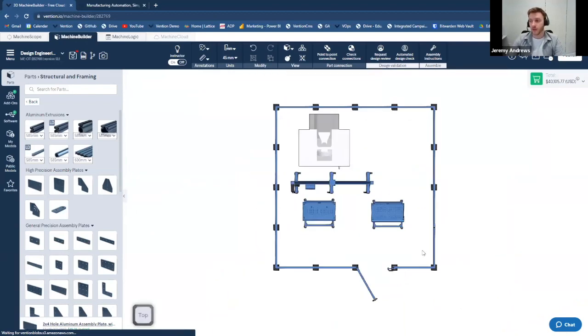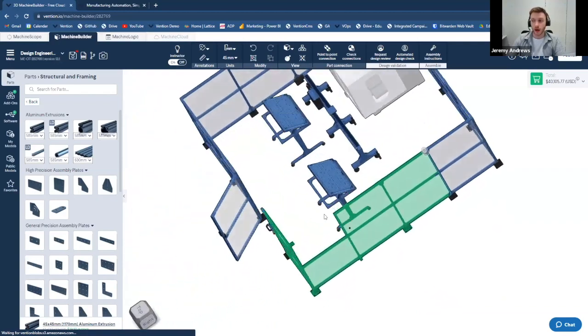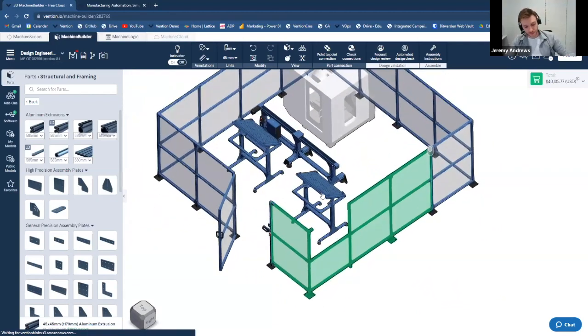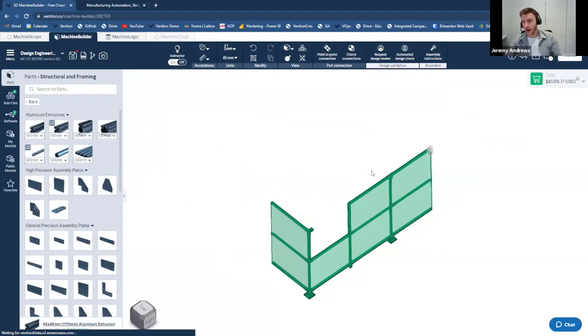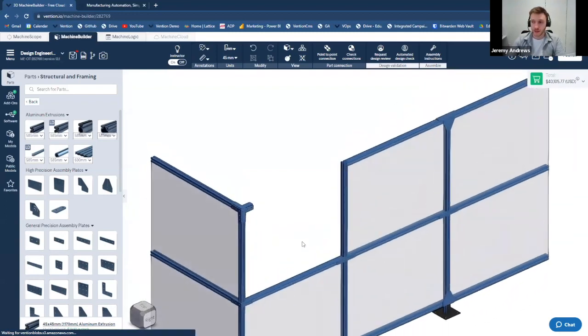So what we can do is actually highlight one of the first shortcuts, which is the ability to isolate parts or hide other parts. In this case, say I want to work solely on this section over here. I can highlight it, then press Control-J to isolate that part of my design. With this, any work that I've done here is reflected in my design, and the rest of my design does not actually get deleted, it simply gets hidden from view and I'm not able to interact with it until I bring it back. So for now, let's finish off this part of my enclosure.